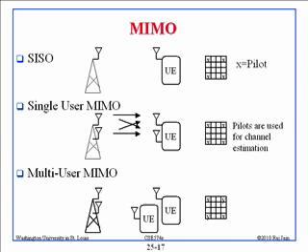And the way it works is, in the previous single antenna case, we had this matrix, carrier versus time. These are subcarriers. Here I've shown 4 subcarriers and 4 symbol times. And we use some of these combinations for pilots. These are the reference symbols, where we figure out if I'm sending you this, what you are getting, whether the channel is good or bad. So we put the pilots, right? From the pilot we can tell the condition of the channel. When you have MIMO, these pilot positions tell us which signal is following which path, and we can get a very good idea of what we call the channel matrix using these pilot symbols.